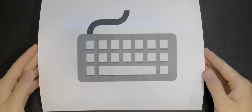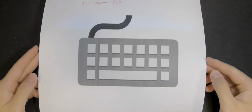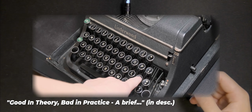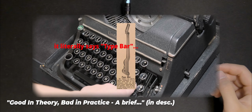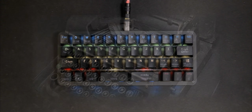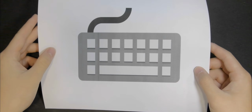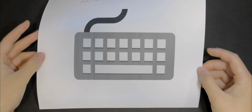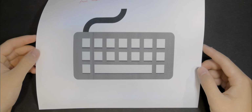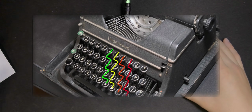So why weren't keyboards designed like this in the first place? Well, it's because of the godfather of keyboards, typewriters. Typewriters worked on a system of keys to key levers to type bars. When you press down a key, the key lever would connect your key press to the type bar, which prints the letter on the page. Now, if we were to use a grid-style keyboard like this one, the key lever that you pressed would simply hit the key beneath it and therefore not work. So to fix this, we simply stagger the keys to the side.